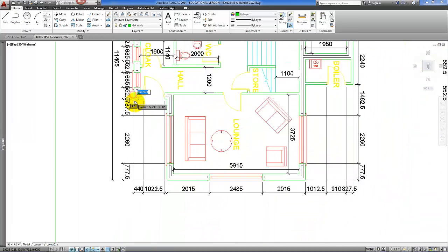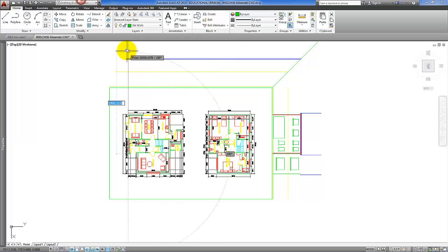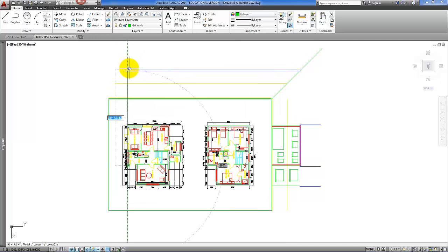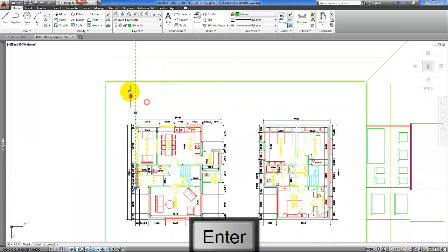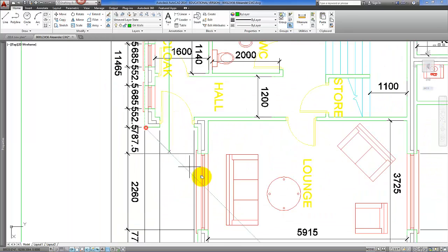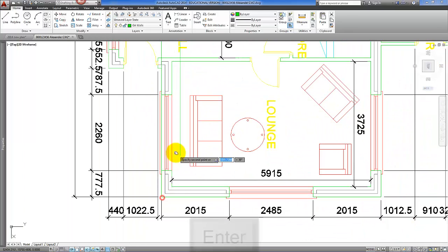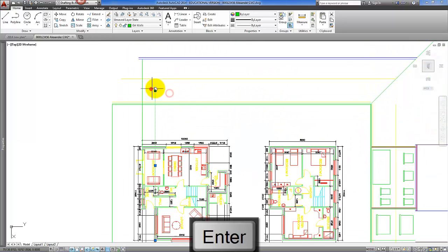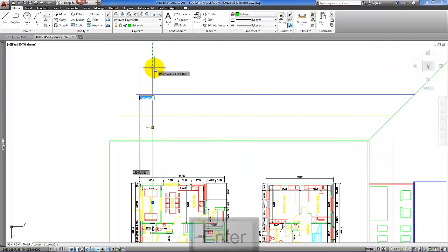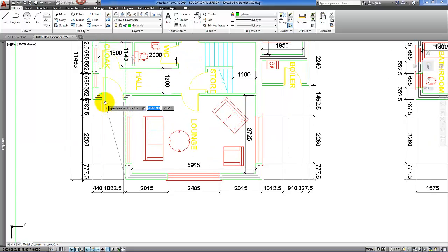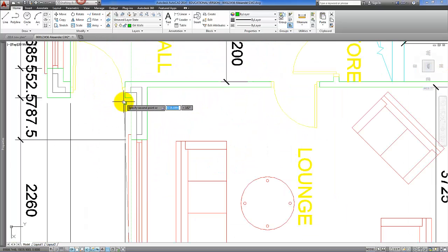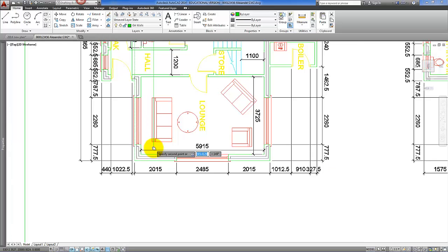Really it should be, since it's that elevation that we're going to draw, and we'll go to the underside of the fascia, and we can select that line and copy it, and really should have made that first line longer, so let's do that now. And we can copy that line to each of the positions where there's going to be a door or a window like the previous elevation.